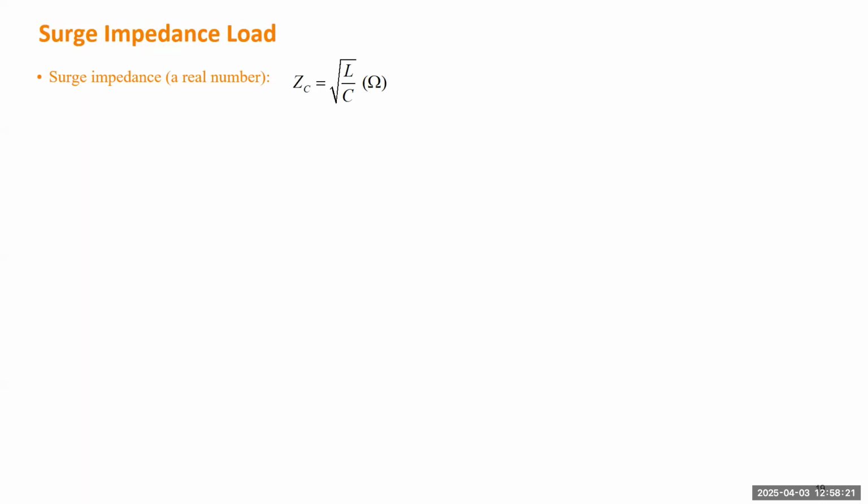Because for the transmission line, if we consider the series reactance along the line and also the capacitance to the ground, the capacitance will provide some reactive power, and the series reactance will consume some reactive power. Those two reactive powers will be opposite to each other. They perfectly compensate. And then for such a line, if you measure the reactive flow, it is 0 on both ends. You don't need to do any control. I won't go into the detailed derivation, but you can check your slides. If you don't find it, I will let you know on which page.